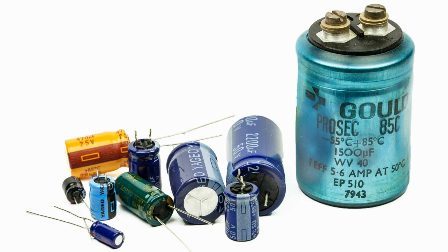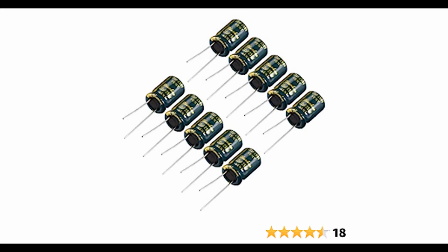Dielectric material. Electrolytic capacitors use an electrolyte, which is typically a conductive liquid or gel-like substance, as the dielectric. The electrolyte interacts with a metal oxide layer on the electrode to form a thin insulating layer. Polarized capacitors are a type of capacitor that has a specific polarity, meaning they have a designated positive (plus symbol) and negative (minus symbol) terminal. These capacitors are also referred to as polar capacitors or electrolytic capacitors.